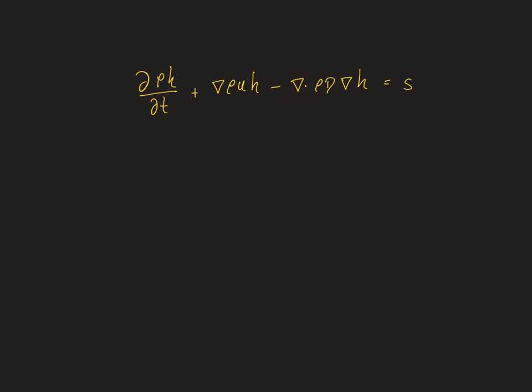Let's put here a source, and for the elliptic equation we just say we don't want to have the unsteady term, so it vanishes and we get the convection diffusion. And just for a more illustrative purpose, we also neglect the convective term and we end up with the so-called heat equation.